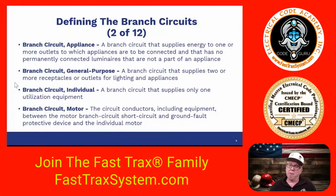Now, motor branch circuits, what are they? Well, they're the conductors, including the equipment, between the motor branch circuit short circuit and ground fault protective device and the individual motor. Okay, so from the short circuit ground fault protection that is demanded by 430.52, from there, all the way, and the components that are involved, all the way down to the individual motor, that is considered a motor branch circuit. And so again, that branch circuit is specifically for motors.